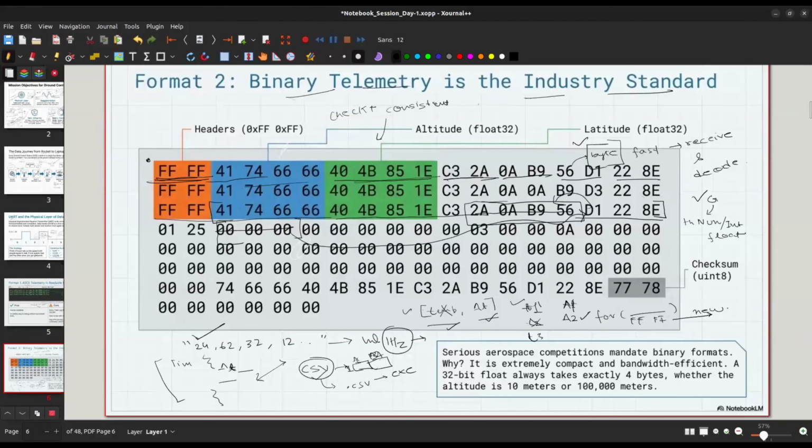Temperature 3, you received, and altitude 3, you received. When your GCS is coded to look for temperature and after that altitude, and it did not receive the temperature, it is going to assume that A2 is temperature, and it will also assume that the next value, T3, is your altitude. And that is so wrong, right? You are decoding T3 as your altitude and A2 as your temperature.